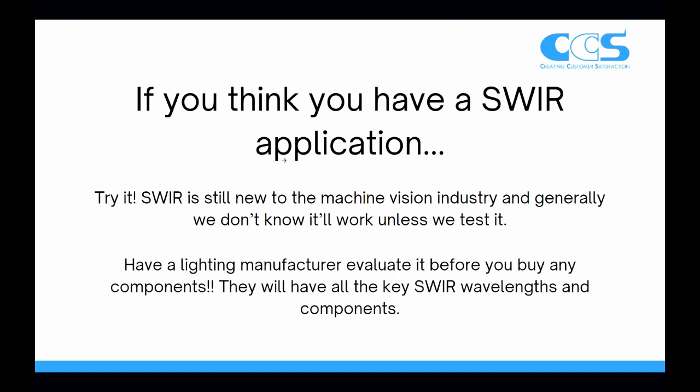Unfortunately, people want to just say, oh, can you just tell me what wavelength and I'll get that one. And no, we really can't. Not only do we not know which wavelength will work, we don't know if any wavelength will work. So it's really important that if you think SWIR will solve an application, to try it out before purchasing anything, because as I said before, SWIR can be expensive.